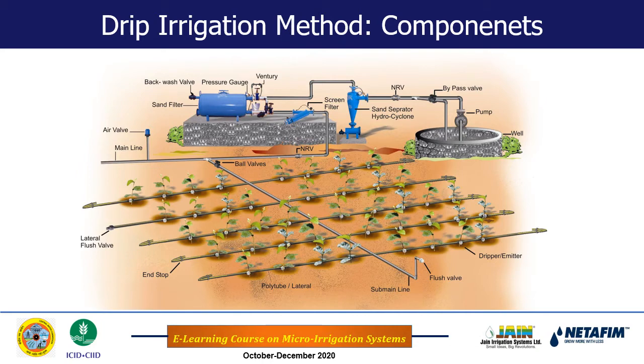So this is regarding the water source. Now if the water source is not in the field, and if it is away from the field, then we have to pump water from the source which is away from the field into the field. In that case there may be one auxiliary pump as well, depending on the distance between our field and the water source. When we bring water from a water source which is much away from our field, then we need to have an auxiliary storage and also an auxiliary pump so that we will have better control.